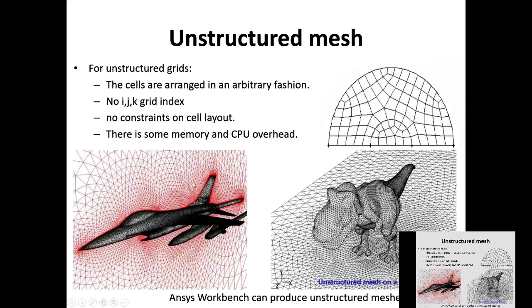If you take this one, yep, you need to resolve the boundary layer here. So that means you need to have a really fine resolution there. Yes. But if you are worried that the boundary layer doesn't extend beyond this point, here, there is no boundary layer effect.